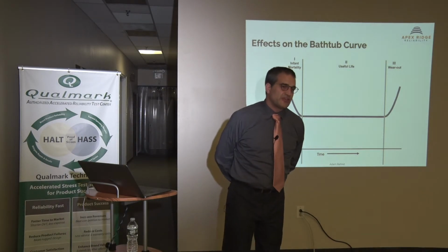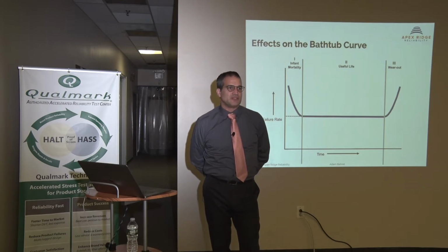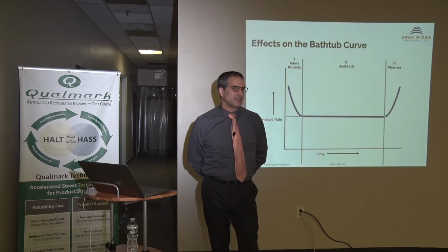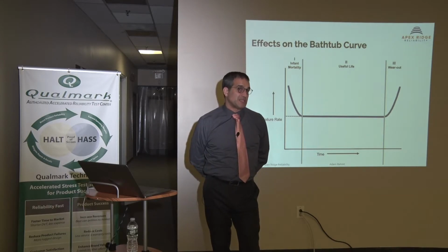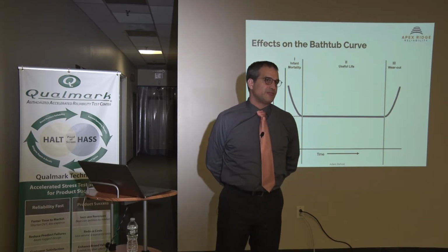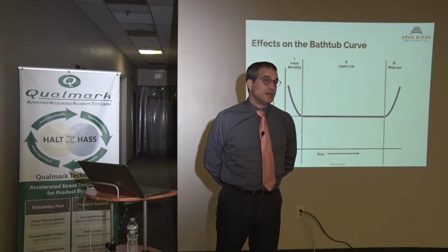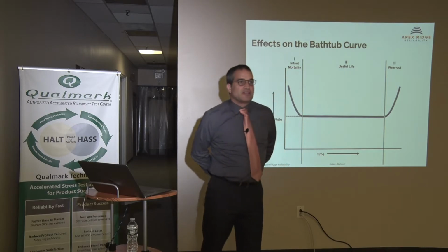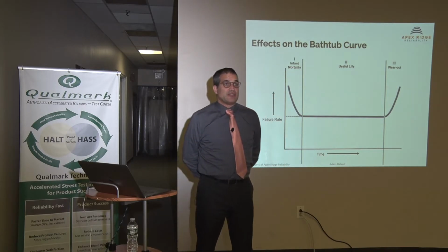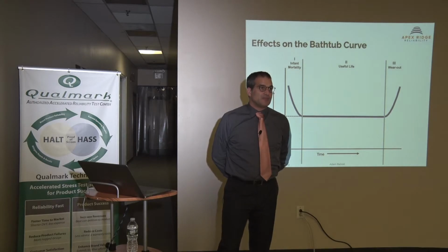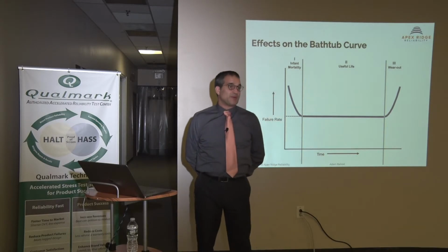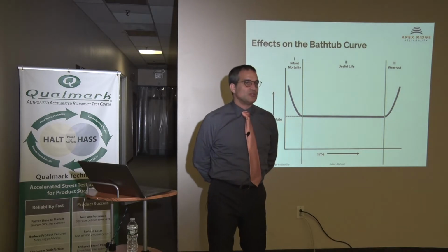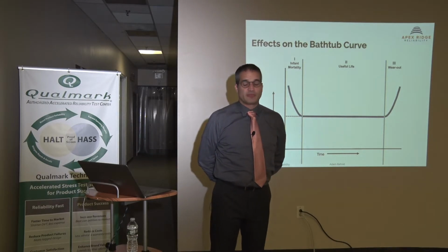And the constant failure rate's always generically assumed because you have a lot of individual behaviors in a product, and when you put them all together, if it's a complex product, you can say it has X failure rate over its life, which is an easy way to measure it and communicate what's going to occur. And then at some point later in life, all these units begin to fail at an increasing rate. They're wearing out, and this will continue until the entire population has worn out. So that's a generic way to look at reliability for a group of products.